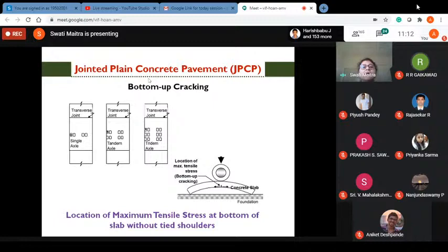So this is a typical chart for estimation of critical stress or flexural stress on the pavement with different slab thicknesses, with a particular single axle load of 120 kilonewton rear axle load, temperature differential of 8 degrees centigrade, without concrete shoulder, and with different modulus of subgrade reaction values. So like this, there are several combinations, and there are a number of charts.